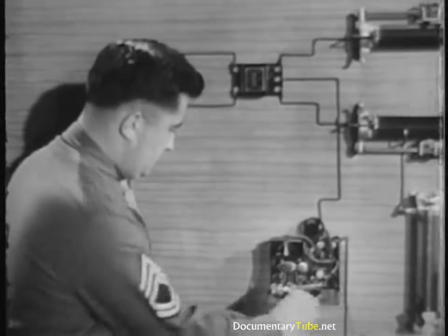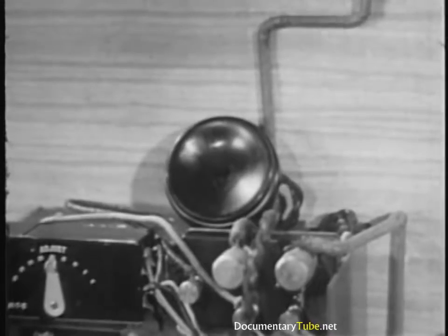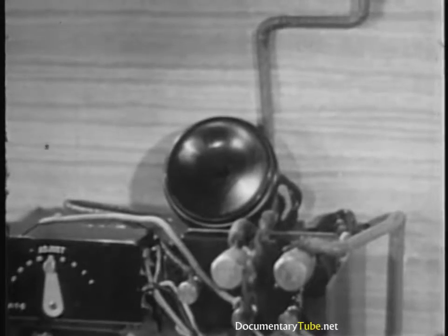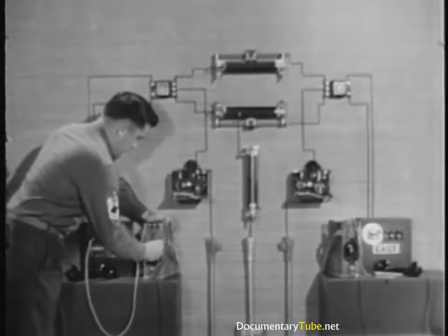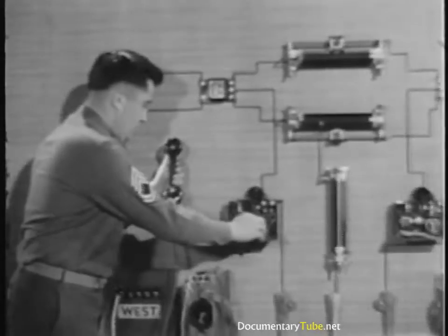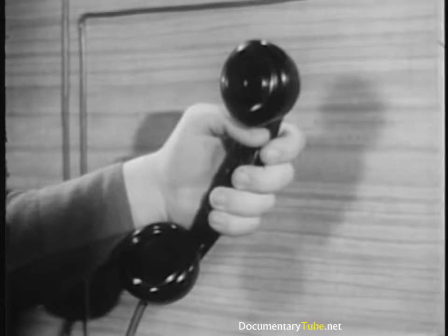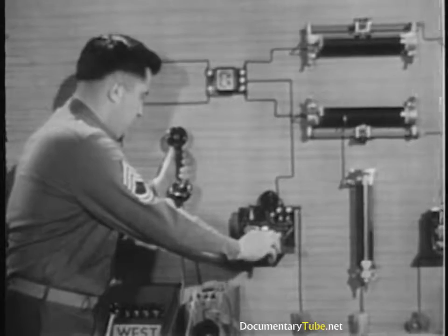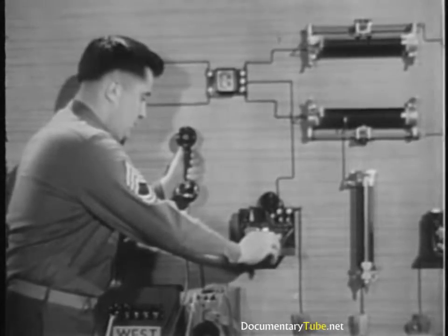Ordinarily, the telegraph channel is still usable unless the diverted ringing current is strong enough to cause interference. The telephone channel is still okay too, but its quality may be somewhat impaired by key thumps. And like any other grounded circuit, it's apt to be noisy. So much for the simplex. Here is what we have seen so far.